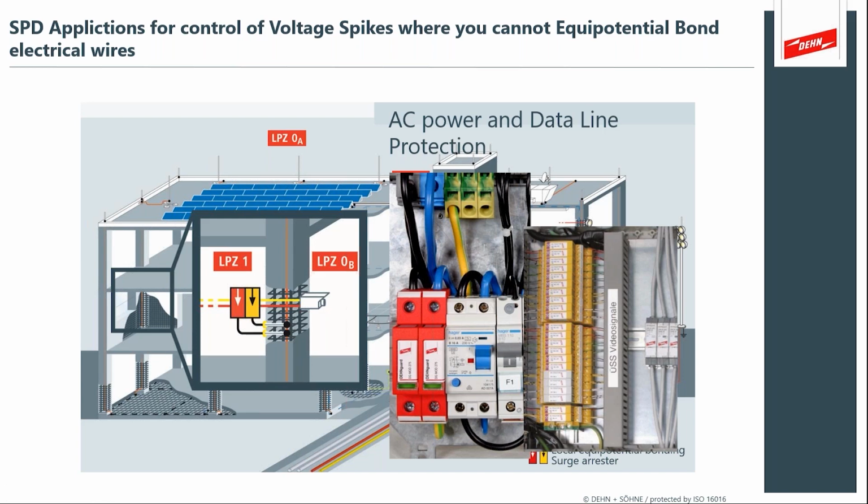And remember, lightning isn't always being conducted into the electrical power. What might happen on a building like this is lightning hits the air terminal, is safely conducted into the soil, but as that lightning charge is attempting to dissipate, it's building what's called a ground potential rise. And so the lightning currents aren't necessarily coming from the power.